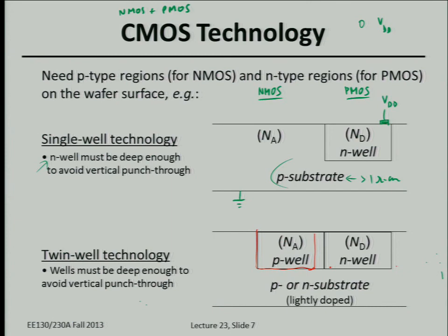Okay, so the question is, are the N well and P well doping pretty uniform across the substrate or vertically? Yes, so locally it might tune the threshold voltage by VT implants, but usually the well doping is the same most of the time across the entire chip for all NMOS devices and for all PMOS devices. That's pretty typical, yeah. The well doping profile is not perfectly uniform vertically, because it's formed by ion implantation, so it's usually more heavily doped up here, and then at the metallurgical junction, it's more lightly doped.